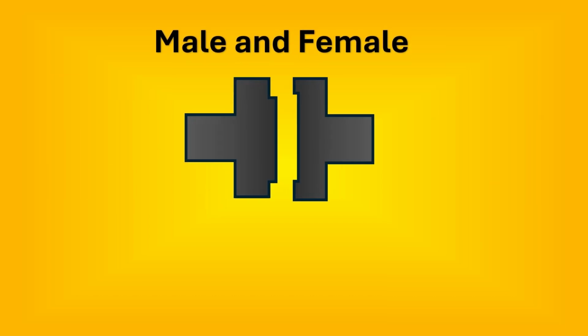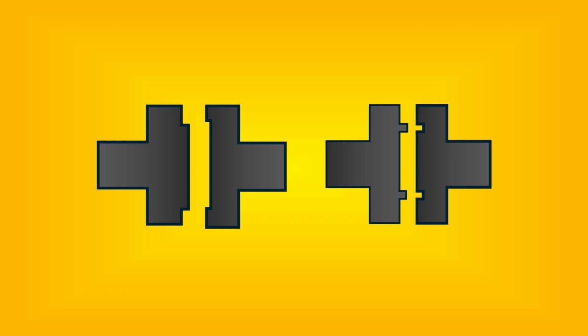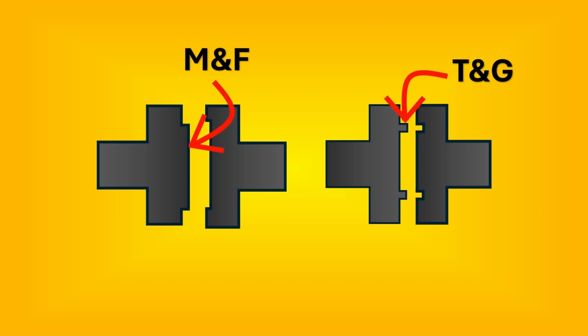Let's look at male and female design. Now the male and female design is similar to a tongue and groove design, but there are some subtle differences. In a male female design, the male part is protruded, and that is a very big design as compared to tongue and groove. In tongue and groove, the tongue has a very small portion that is protruding out and the groove accommodates it. So this depends on the type of application that you are working on.